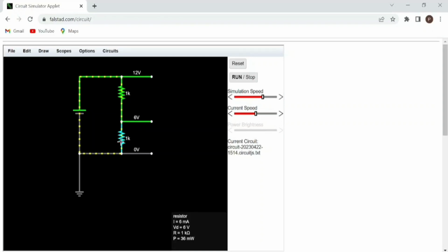And how do we get to know the voltage drop across a resistance? I just subtract this voltage minus this voltage, and I get the voltage drop across this resistance. Similarly, this minus this, I get the voltage drop across the other resistance. So that's what is happening. As both the resistances are equal, the voltage is getting divided equally. And whenever you are doing voltage division and you want to find the voltage across any resistance, you need to follow just one thing. You take the total voltage applied across both resistances, multiply it by that resistance, and divide by the sum of the two resistances. That will give you the voltage drop theoretically.